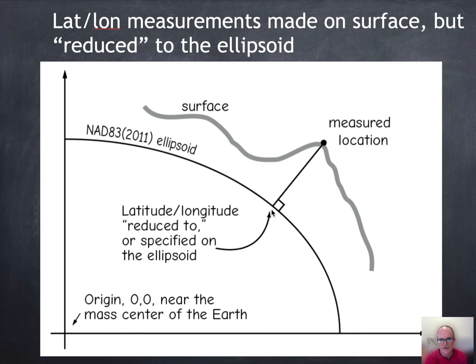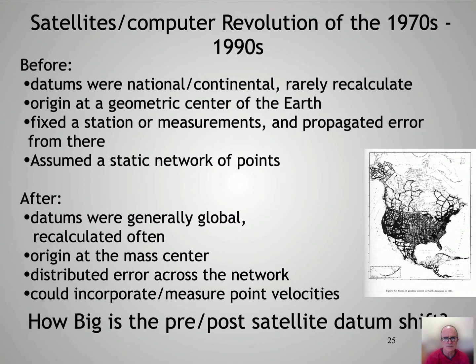Right? Heights we measure relative to this point here, this point on the surface. This is our reference surface, right? So remember, that's the way we define a datum: a reference surface, then well-defined points on it. So any location here, we're measuring relative to some other location that's in our well-defined set. Okay, it's GPS towers now. It used to be those benchmarks from physical surveys before.